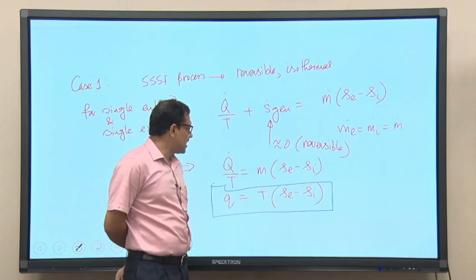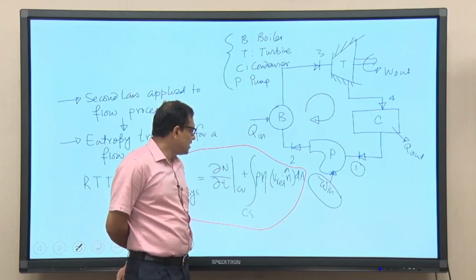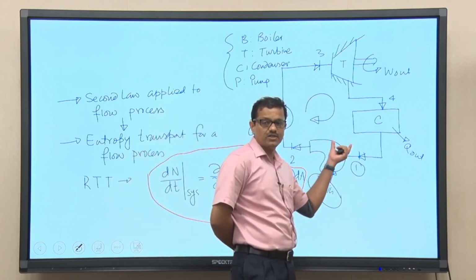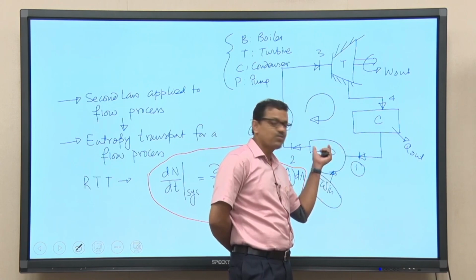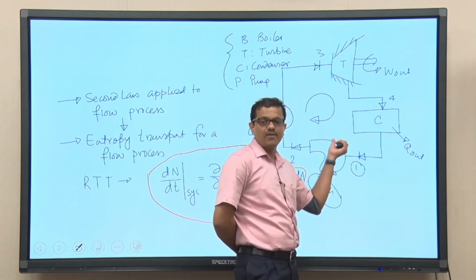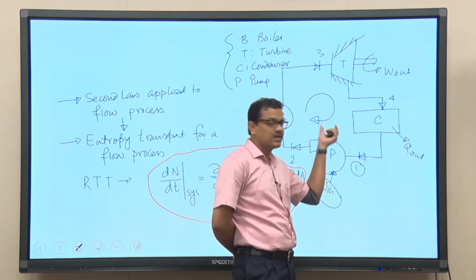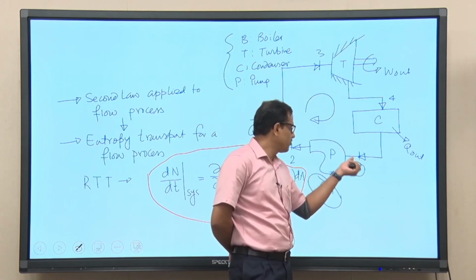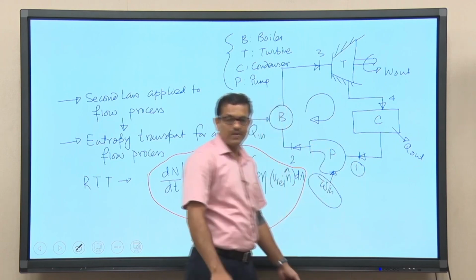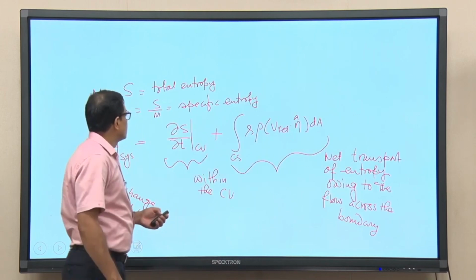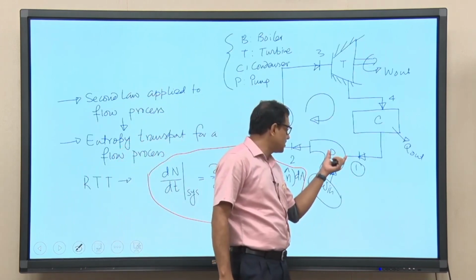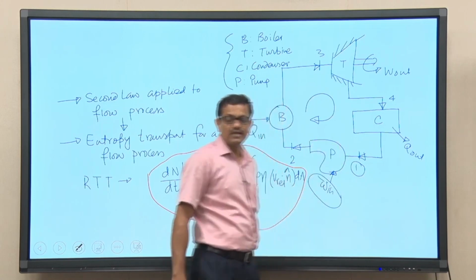You try to understand, we are trying to establish the expression of W for a process which is there in a pump. In this process pressure is changing. So, the sole objective of having this particular component in this circuit is to raise pressure from point 1 to point 2, or state 1 to state 2. If pressure is changing, and this is a flow process, we need to write dH.